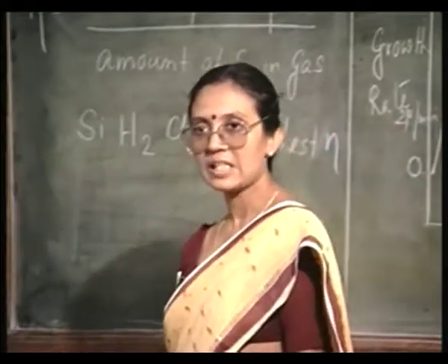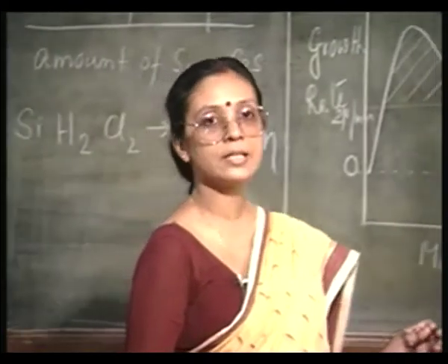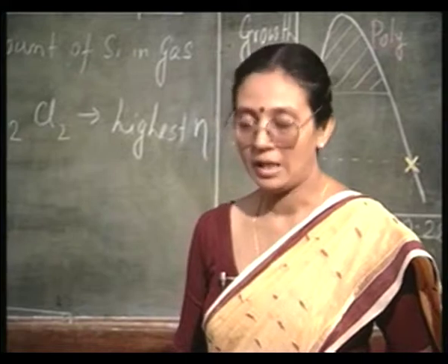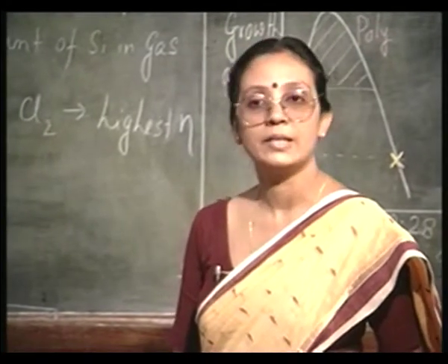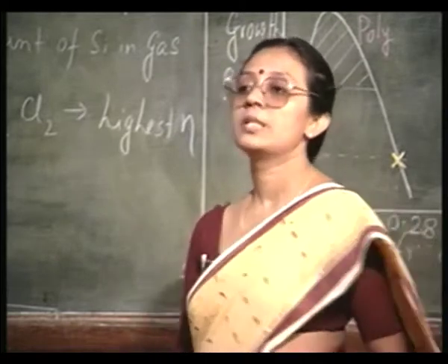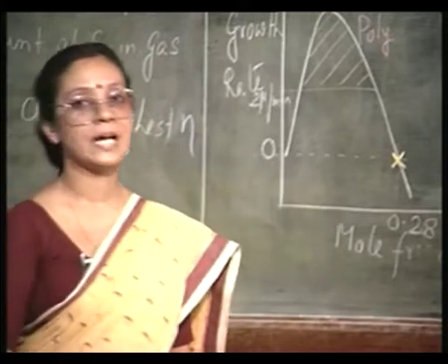So, is there another route by which we can still have silicon deposition, but without the presence of HCl? The other route is the pyrolytic decomposition of silane.